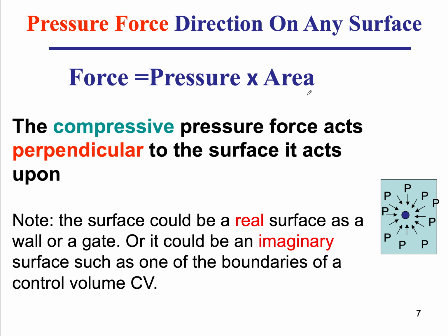So if you remember those two, these are the two primary fundamental pieces of information that we will use throughout this chapter in our solution of fluid problems. One, the pressure is compressive, and two, it's perpendicular. And as long as we have a static fluid, we don't have any shear stresses. So the only interfluid force is the pressure force.